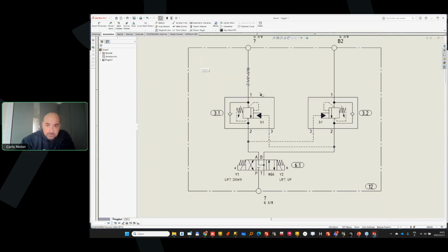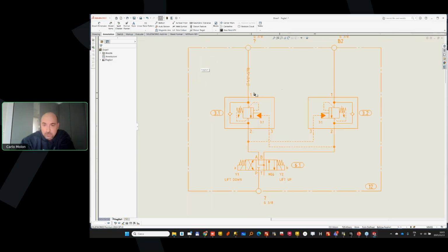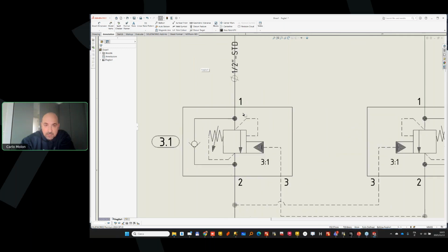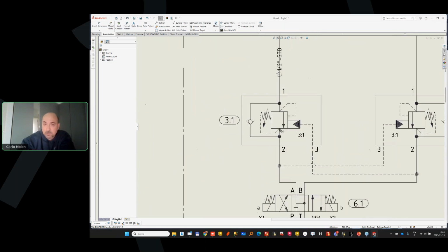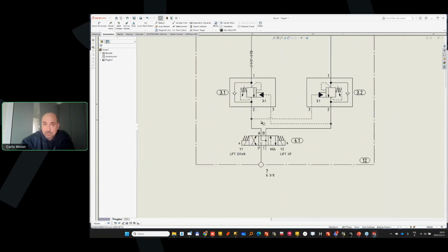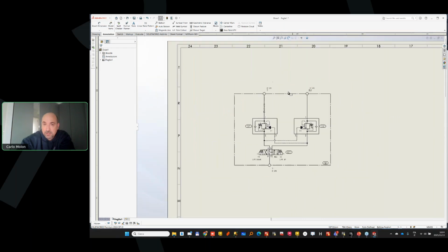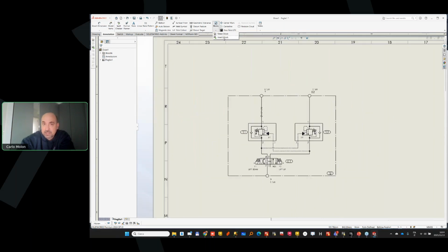And this is fantastic because it was not working, so I was not able to make it work. If you notice, we changed the technique. The problem was with hatches, because hatches in SolidWorks 99% of the times in metric OS will import hatches as not recognized. So we changed the hatches with this simplified DWG into this surface, which plotted will be full color, but in this way we can really simplify it a lot. And the ability to import a diagram as a block is really